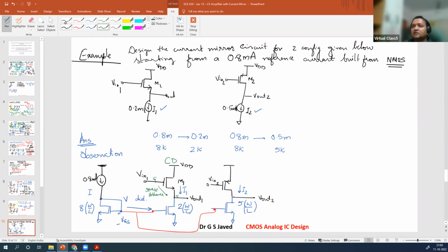Now if you look at this circuit here on the right side, Vin2, the input is applied to the gate. Output is taken from the drain. What does this mean? This is what is now common to both these places? Again, the source. So it is a common source circuit. But remember, one is an NMOS, the other is a PMOS. You should not say that they are commonly common to the drain or power supply. So how can one be common drain and common source? Note the transistor, in one case it is an NMOS, in the other a PMOS.